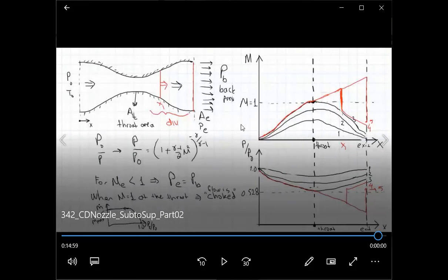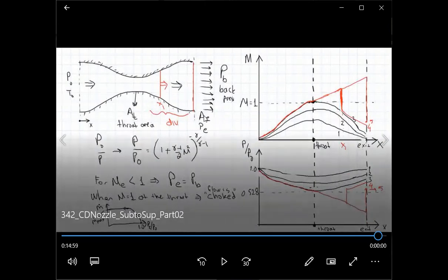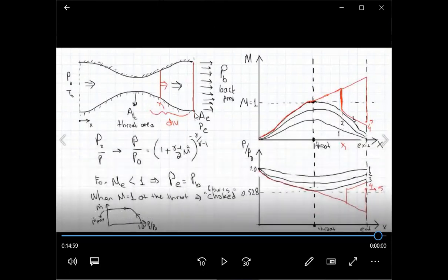In order to obtain that just before the test section, we generally place a converging diverging duct. So the exit of the duct should provide fully supersonic flow. We really do not want this normal shock wave there. Therefore, this shockless, fully supersonic condition can only be obtained at a specific P exit value.